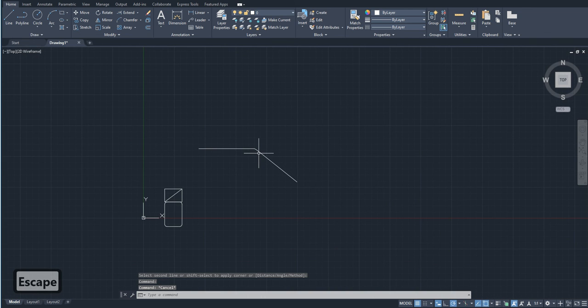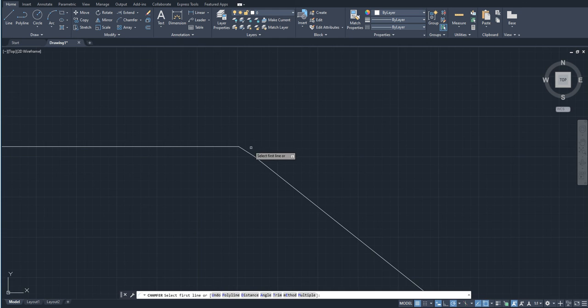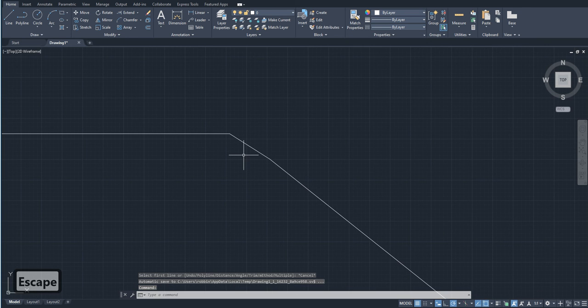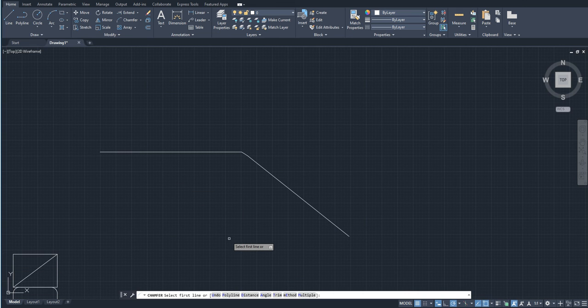If I just enter the chamfer command again, you can see it has similar options to the fillet command. It works in a similar way. I hope you practice on your own and understand how these commands work, except that one option you have over here is the angle. Over here I specified the distance initially. I can also specify the chamfer using the angle. If I just press A, enter,